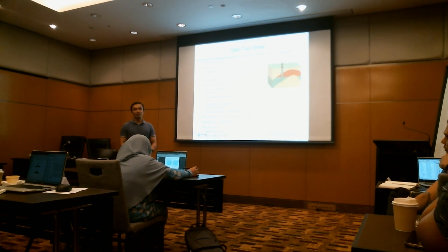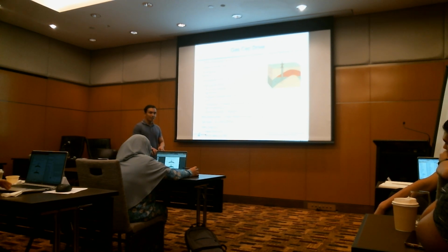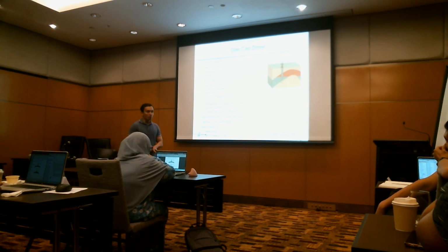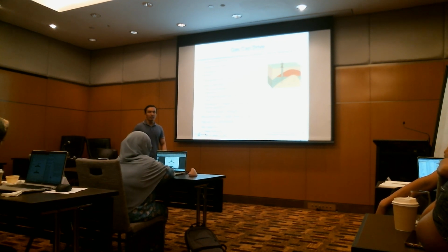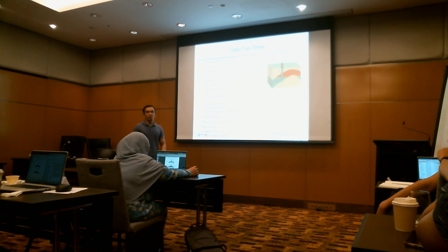The parameters, like permeability in your aquifer, will also impact your water influx. If you have a big aquifer but low permeability in your aquifer system, you expect your water breakthrough will be delayed, and will come much later. But if you have very high permeability in your aquifer, you expect that as soon as you produce, the water starts to come in early.